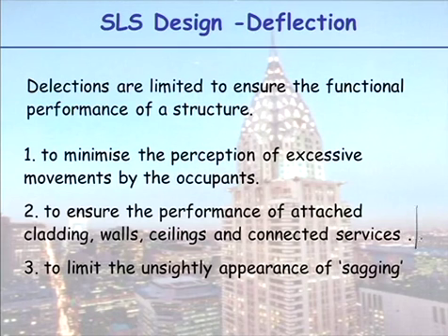Another reason is that if we're in a building and the roof above deflects too much under wind load, the ceiling's going to start cracking. Also, if there are any connected surfaces in there, pipes or cables, that movement could cause those things to fail. And finally, it's a purely cosmetic reason. No one likes to see a sag. Saggy baggy. So we like things to look horizontal.